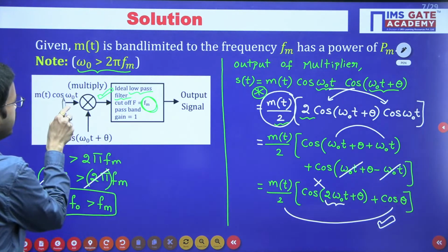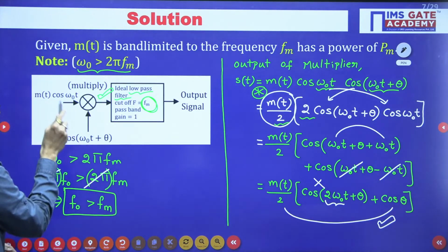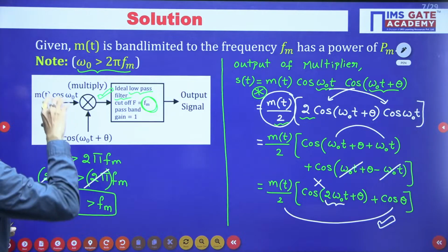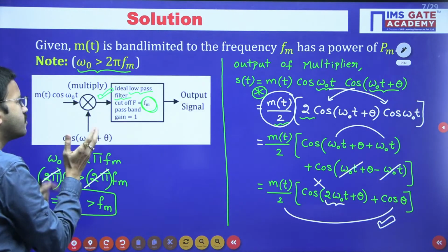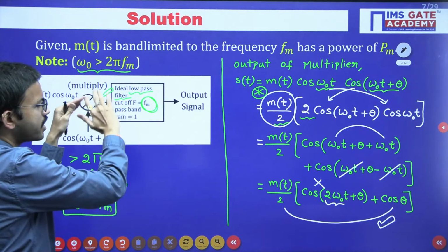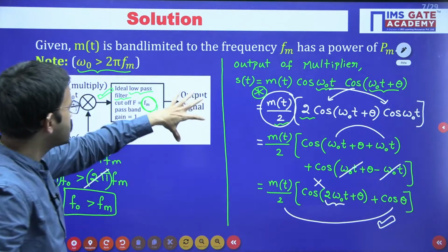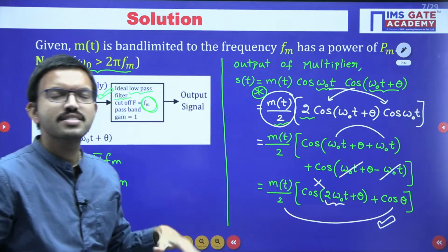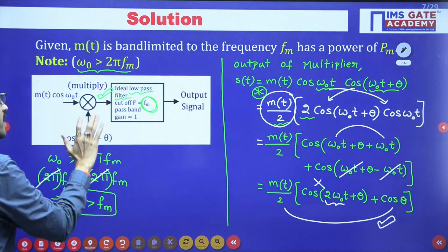If there is no phase difference between these two carrier signals, that means the carrier used at the transmitter and the carrier used at the receiver are in synchronism. That is the reason the detector or demodulator that you use to extract the message signal is named a synchronous detector. Whenever there is a phase difference, we consider it according to that phase difference.